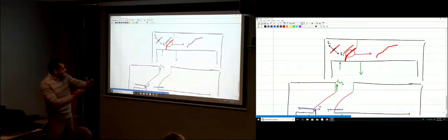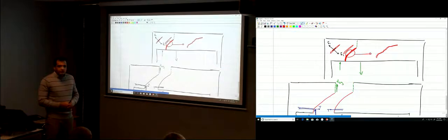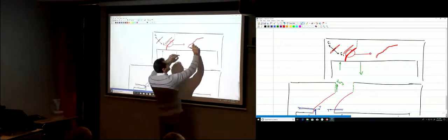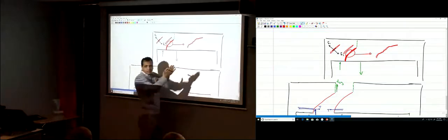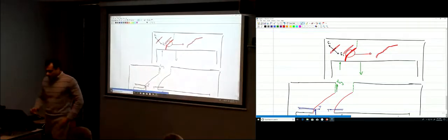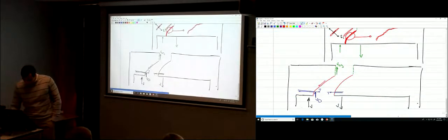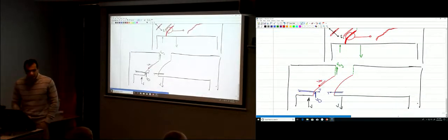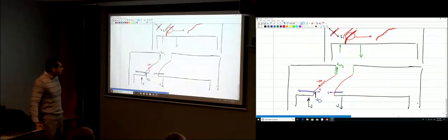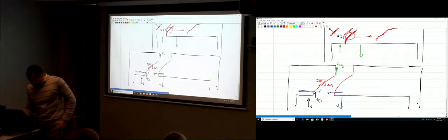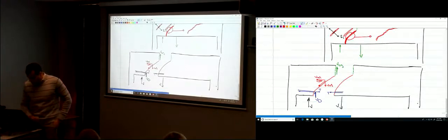So actually, when those two surfaces try to slide along each other, okay? There is aggregate interlock. Those surfaces, there will be some aggregate interlock, okay? So that will give me some force, VA, the shear force for the aggregate interlock. The vertical component of that is VAY, and the horizontal component is VAX, okay?